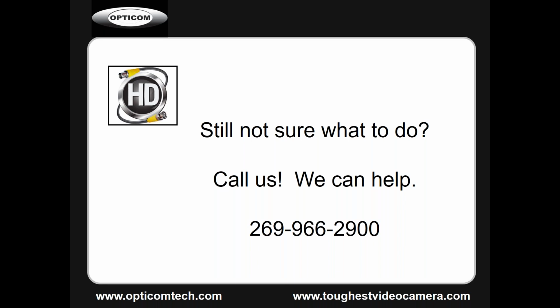But again, the first step before you even think about ordering any kind of camera from anyone, when you're trying to switch out your existing system, is to make sure that you switch that processor out. So you've got some sort of a hybrid that will let you do analog and TVI, so you can make a smooth switch. You replace that, and then you can add the TVI cameras down the road. If you've got that hybrid unit, it'll accept all of your analog stuff that you already have in place. So that's really important as your first step when you make this transition.